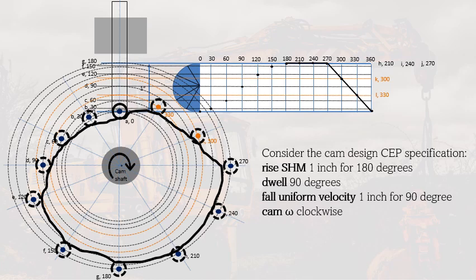If we're going to use a French curve, the curve will be smoother than this one. So make sure to have a smoother cam profile when you draw it, especially on paper. You can use a French curve to make it better than this. But for the sake of instruction, this is how to draw the cam profile if you have simple harmonic motion and combining it with dwell and other motion for a roller follower.